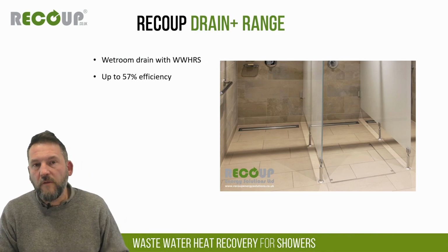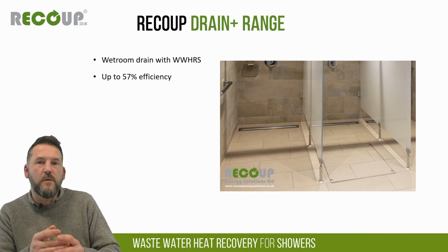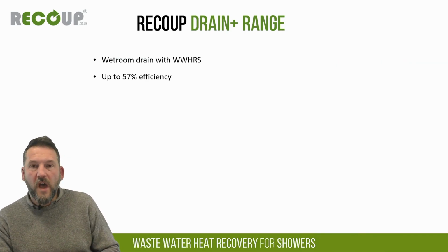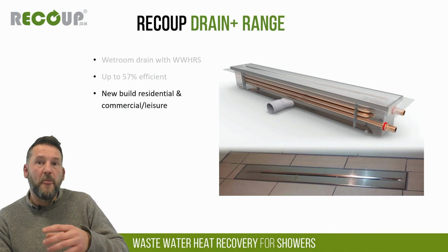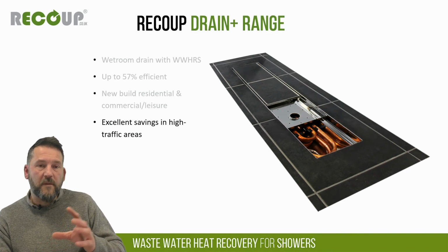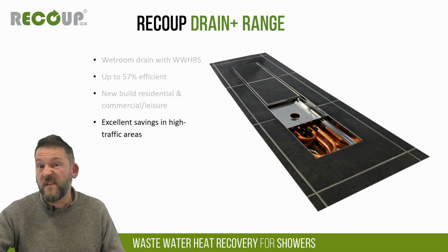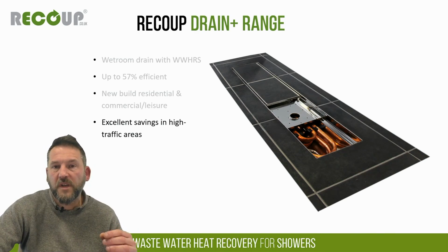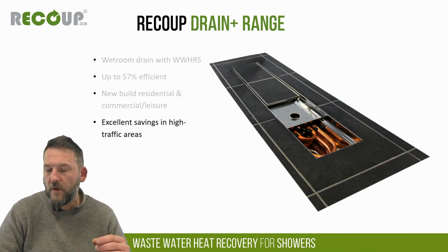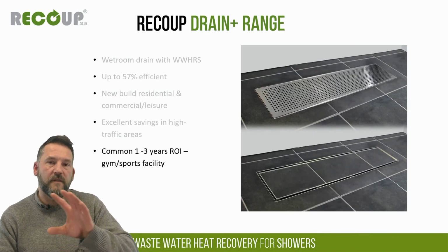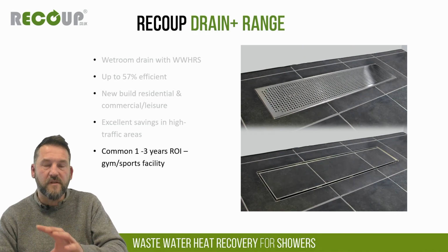And then just for completeness, not really used so often on residential, but we do have a range of wastewater heat recovery integrated wet room drain channels. These are used primarily for communal showering environments, but certainly anywhere where there's tiled wet rooms or vinyl wet room floors, these units can be used. They're very robust. They're absolutely fantastic for non-residential settings, as I said, changing rooms. As you can see here, all of the wastewater heat recovery element is located within the main body of the unit, and everything is completely accessible. So these are a great range of products, with efficiencies between about 35 and 57%. So again, market leading efficiencies on the highest efficiency model.